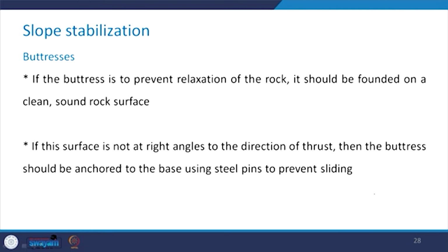Now, if the buttress is to prevent relaxation of the rock, it should be founded on a clean, sound rock surface.